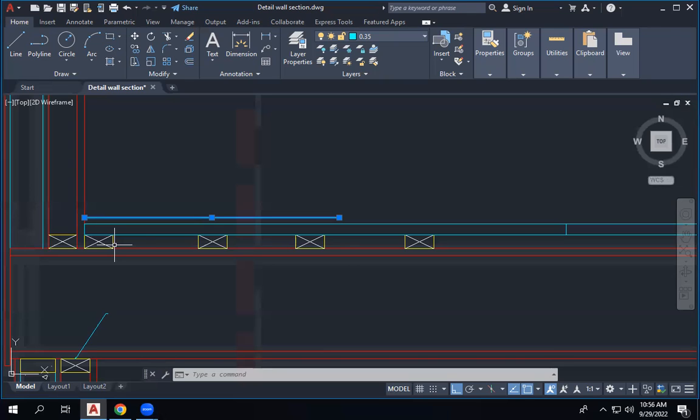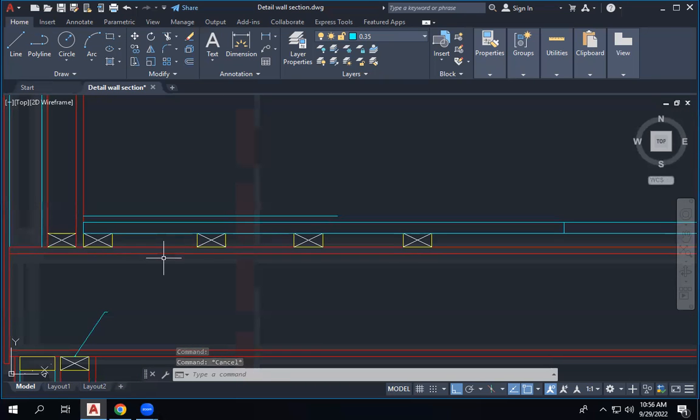It's like, just think about the staircase. Staircases you have more than 1 inch. How thick is the layer of the studs? This one, no, this one. Yeah, this one take it at 1.5 inch. And then the finished work. The finish, it depends on what you choose. So if it's a carpet, less than. The tile that we did down at the bottom, it was 1 inch. So you take the same. If you are doing the tiling on this floor as well, then you take this one.